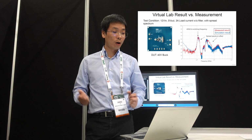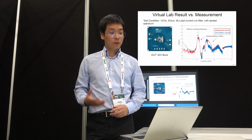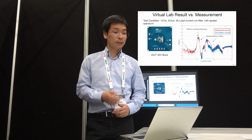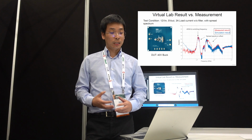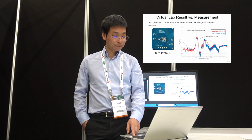So based on that, you know your raw EMI data for the board, and now you can start to design your EMI filter accordingly to optimize your board. You can also throw your EMI filter parameters into the simulation and see the final result of your EMI measurement.